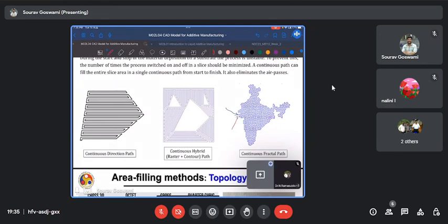Now, in this particular example, the start and end points are close by. This need not be the case, but we see that the entire curve has only one start and one stop point, and there are no lift offs in between. So once the complexity of the pre-programming step is overcome, this toolpath deposition strategy may actually prove pretty helpful as it totally eliminates any lift offs. But again, finding such paths for a general geometry may not be as straightforward.